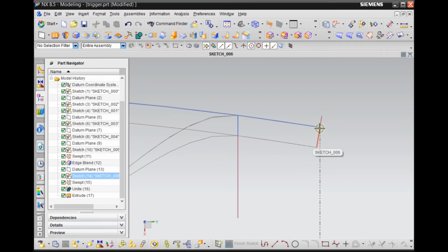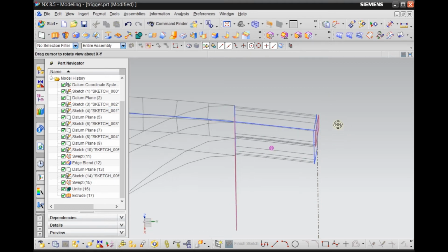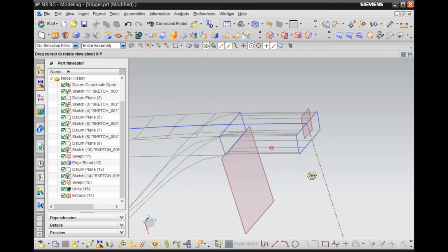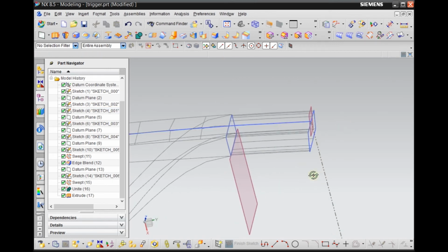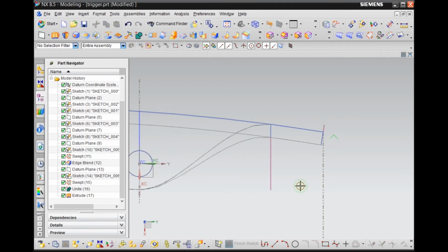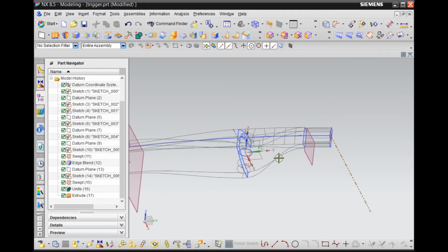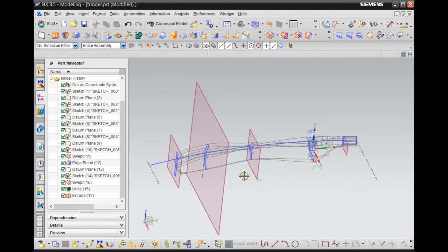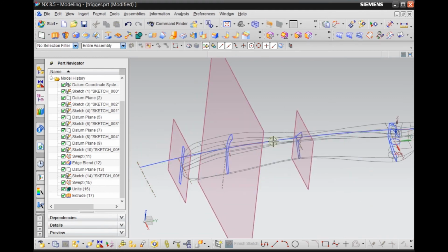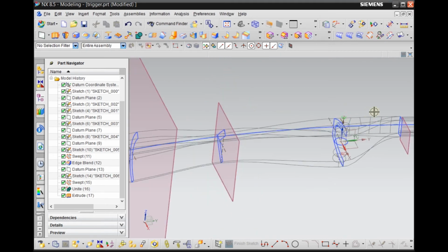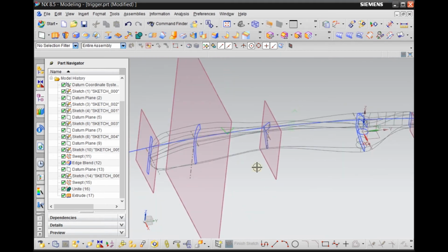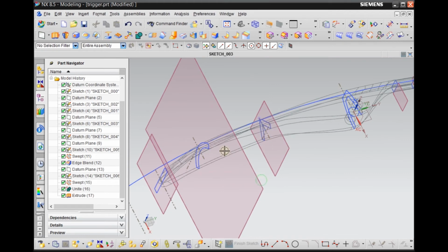When you create a datum, you can create it as on curve, so this surface is going to be normal to this curve. That's how you create multiple cuts, multiple cross sections, and once you get all the dimensions from that IGS file, you can draw those cross sections. You can see 1, 2, 3, and that's the one we just measured.